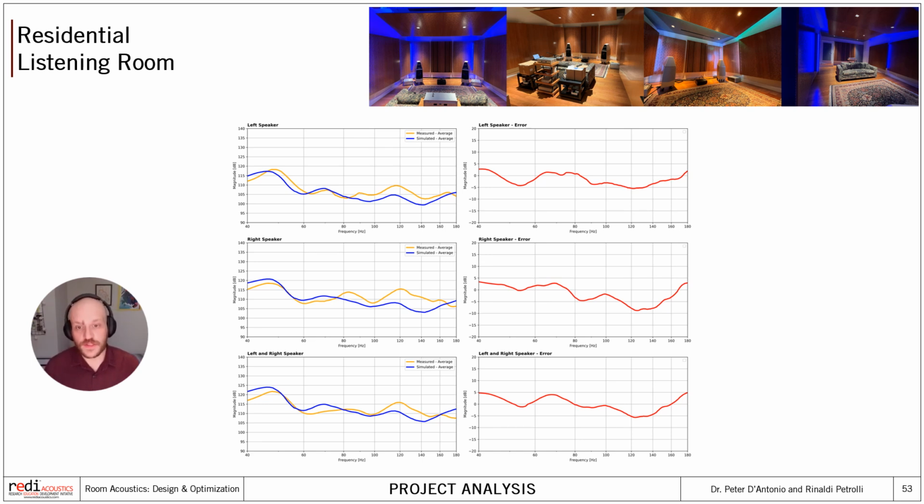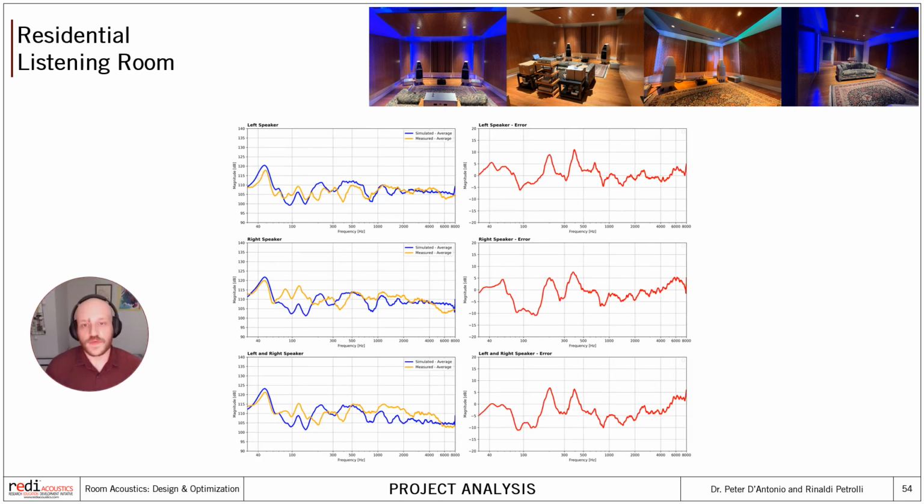In particular, we don't always have precise information on aspects like crossover frequencies or directivity patterns, which are usually more readily available for larger line array systems. And this makes it challenging to predict exactly how the speakers interact with the room, possibly leading to some of the discrepancies we observe. And here we have the full band frequency response comparison between the left and right speakers.